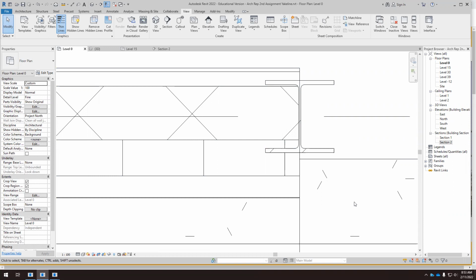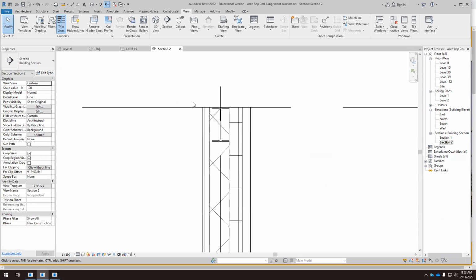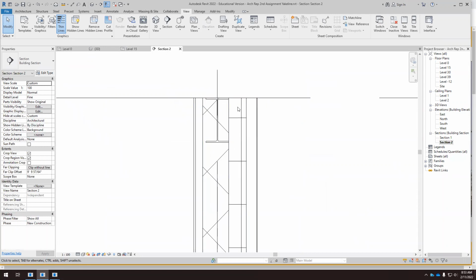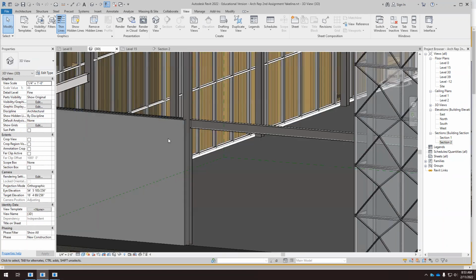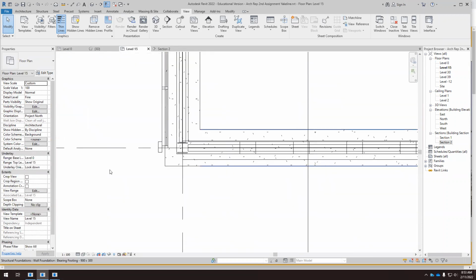That happens because the steel columns and the steel beam don't have the same size. It can happen. It comes with calculations, so it depends on the loads, the beams and the columns. They don't have to be the same, okay? But I have to make a decision because this is not acceptable. It works in section because I don't interrupt the thermal insulation, but it doesn't work in plan.